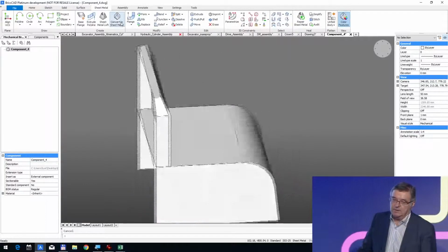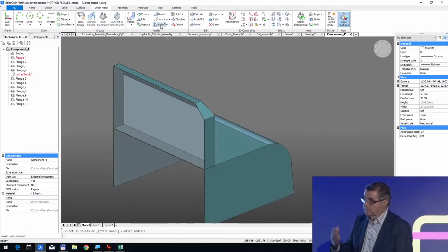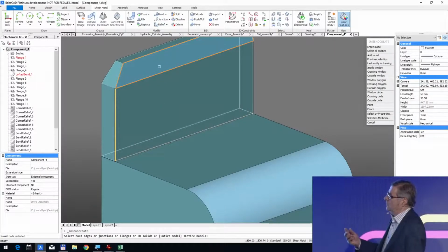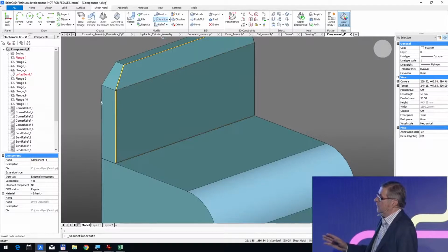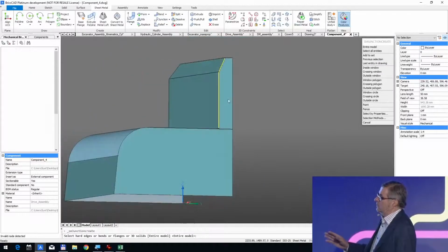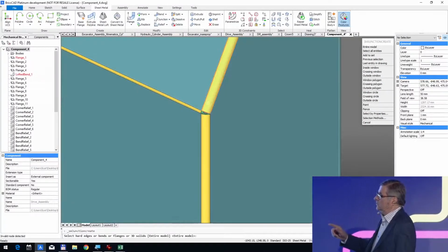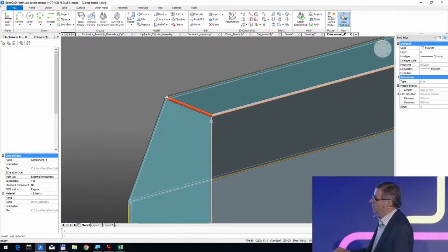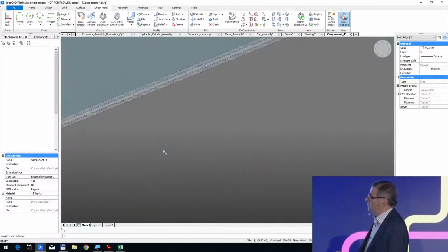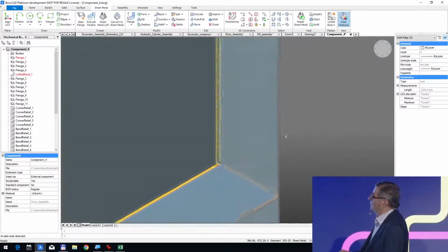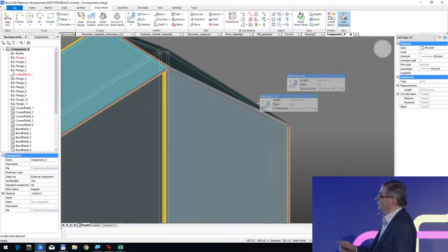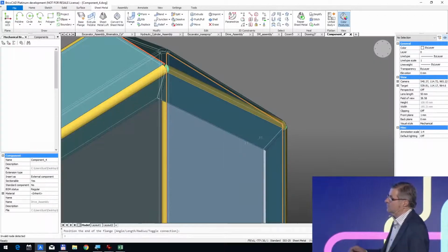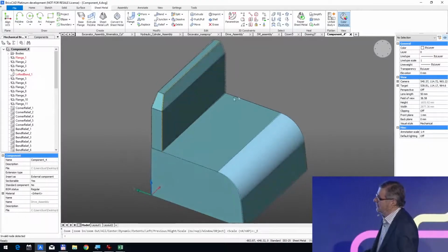And then we will apply our powerful sheet metal features. Then just by clicking, all the bands are created. Automatically, the junctions are created, and we can switch a band to a junction to be accurate. Then we can add on the back 4 new flanges, 5 new flanges, and you see that the miters are created automatically. It's magic. And of course, the part can be unfolded.